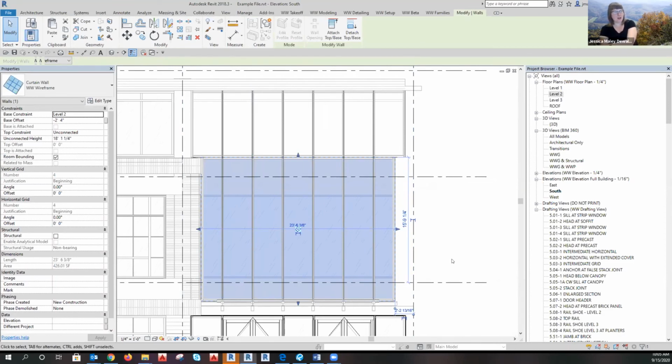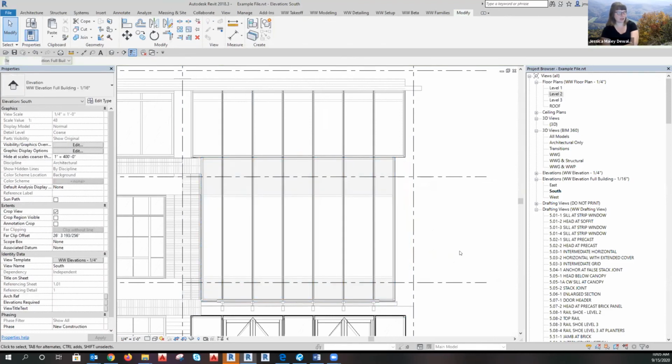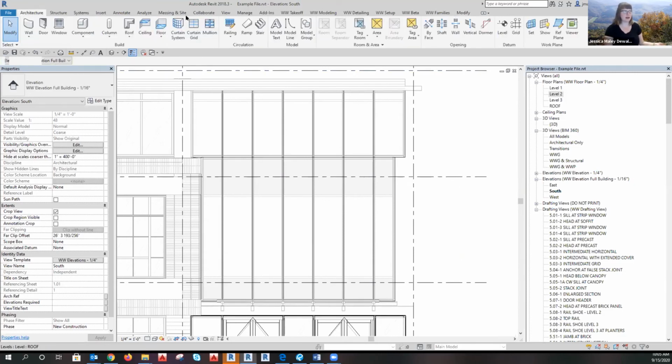Okay. So we've got this bottom curtain wall, and now we need to add our horizontals. So if anyone is familiar with our old process, you know, we would go through a lot of grief to add our horizontals in a certain way. With Quasar, again, it doesn't really matter how you add them. We just need to put curtain grids everywhere that there's a horizontal.